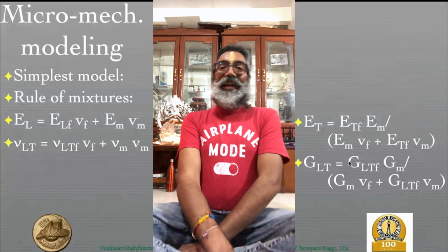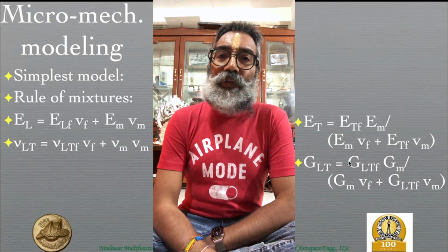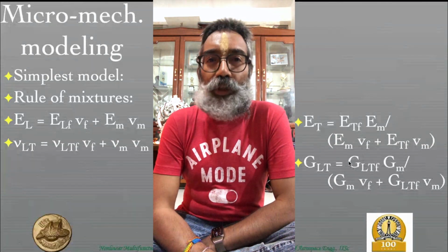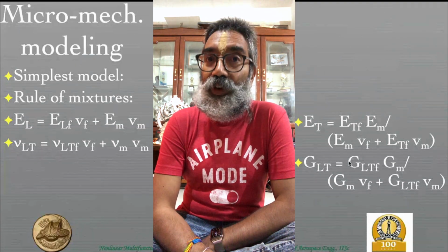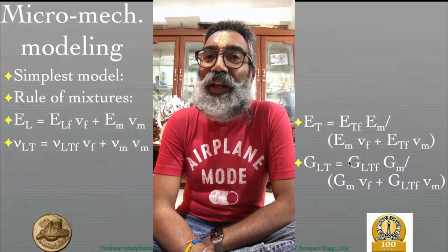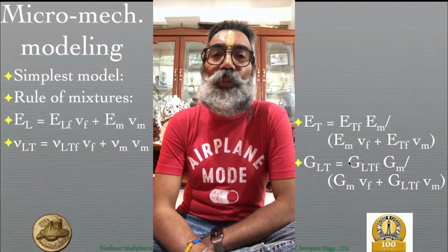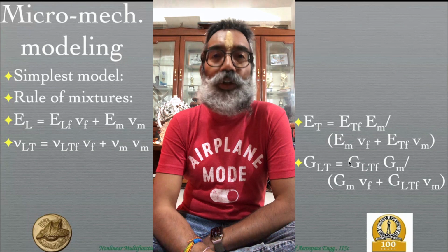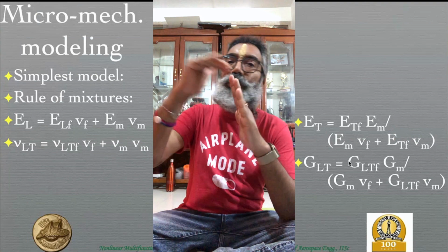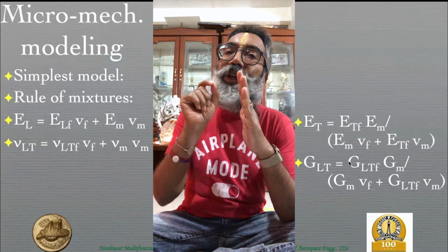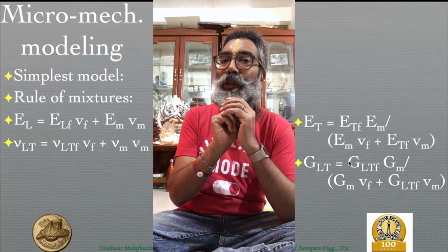Excellent point. See, there are two answers to this particular question, or two parts to it. First of all, recognize that whether it's the stress, strain, or the moduli, all of these are quantities at a point. What we are showing are infinitesimal elements. So the shape of that element can always be taken as a cuboidal structure, even if the overall structure is not cuboidal and has edges which are not perpendicular to each other. It could be a trapezoidal structure, but we are interested in what's happening at a particular point or a particular cross section. We can take a rectangular situation over there.